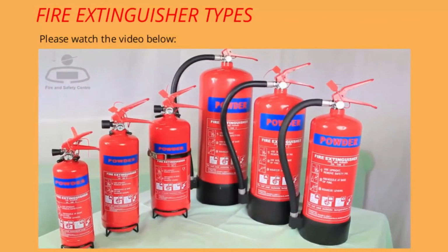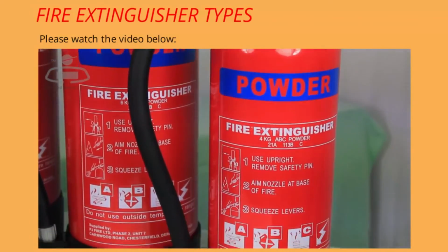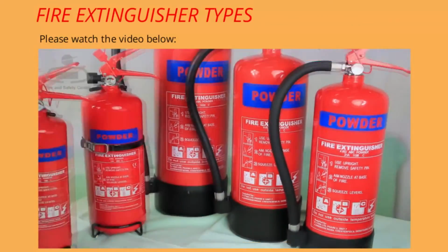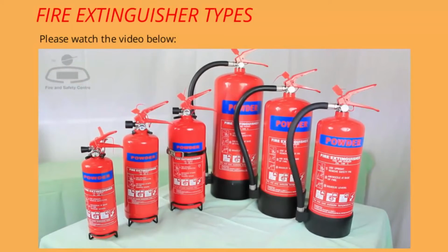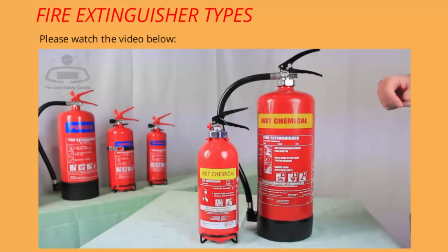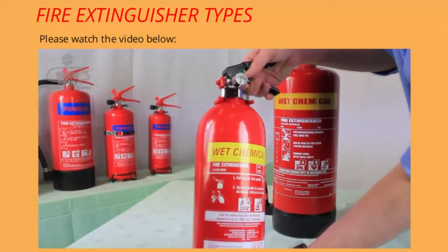Dry powder fire extinguishers are colour-coded blue and are available in a wide choice of sizes and are very versatile. You can use them on fires involving flammable solids, flammable liquids and also flammable gases such as propane and butane. They also work on fires caused by electrical equipment, but unlike CO2, the powder congeals under heat so can leave a sticky residue. Last but not least, wet chemical fire extinguishers are colour-coded yellow on the identification panel.